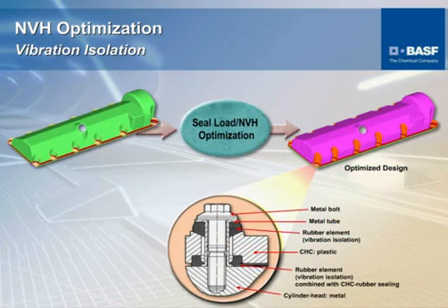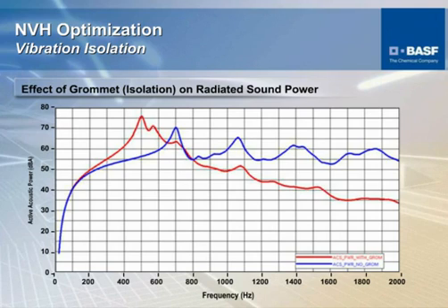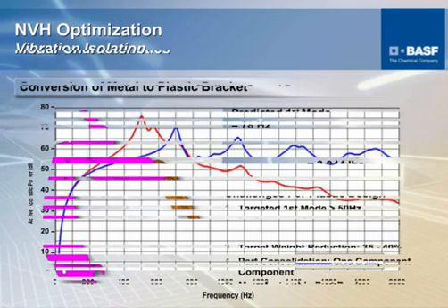Another example is valve cover vibration isolation, looking at different techniques to secure that one and get the reduction in the vibration. By doing the proper adjustment to the molding method, we were able to reduce the actual vibration level significantly, as shown here in this graph.